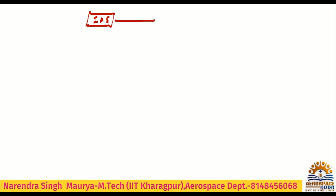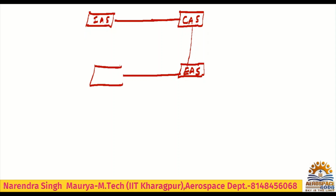After correction you will have calibrated airspeed. Again you correct this calibrated airspeed, so you will get equivalent airspeed. And again, after some correction, you may get true airspeed. So these are the different airspeeds. We have to see how they are related to each other.